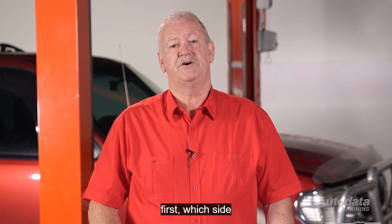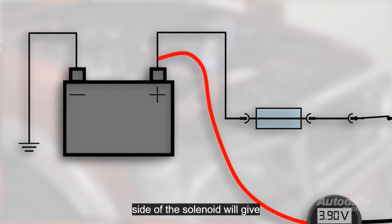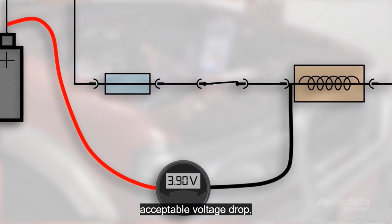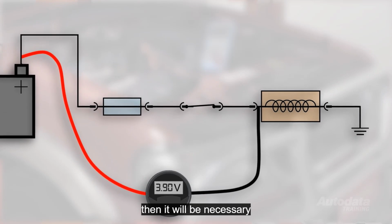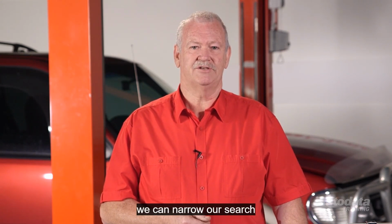First, which side of the load is the excess resistance on? Measuring from the battery to the positive side of the solenoid will give the voltage drop on the positive side of the circuit. If there is an acceptable voltage drop, usually no more than 3%, then it will be necessary to check from the negative side of the load to ground. Now that we know which side the fault is on, we can narrow our search.